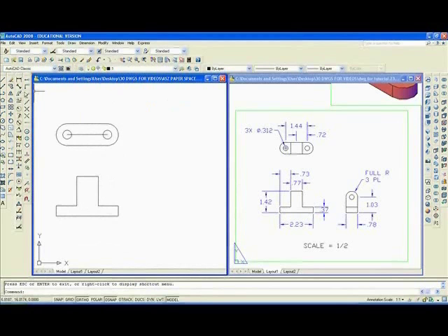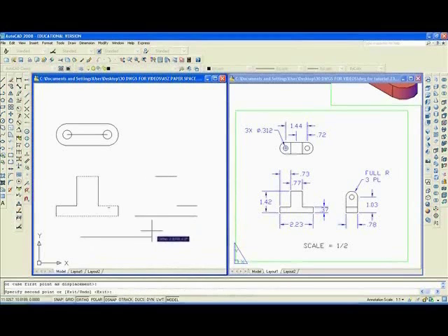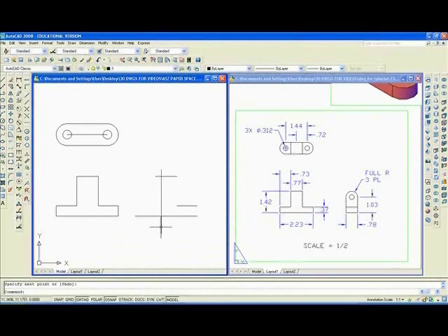I want to copy these two lines, might as well the third one. Drag them over here somewhere. Hit escape, then draw a line, L enter, anywhere, like that, and offset that line 0.78. And we can extend, escape, EX, enter. We can extend to there, that line. And I suppose we might as well fillet radius 0, clean up all the corners.